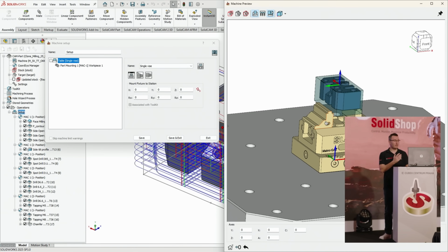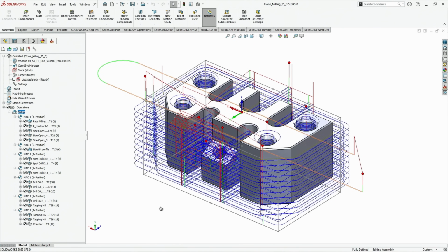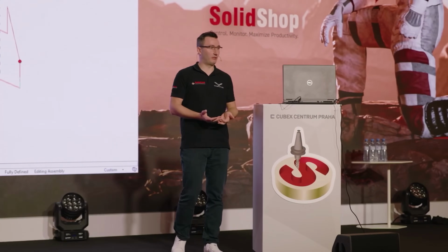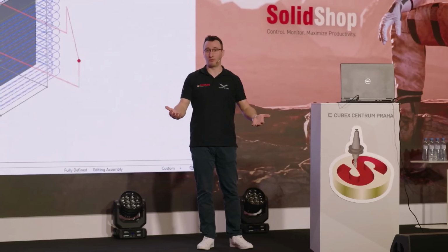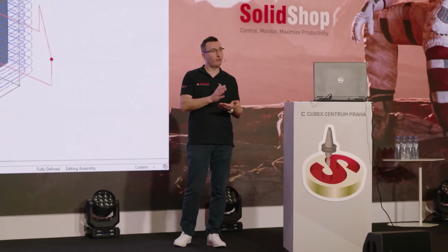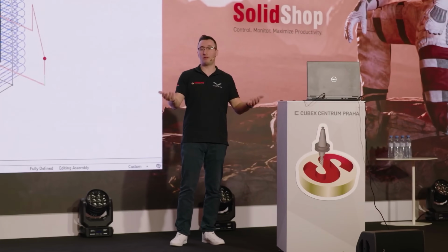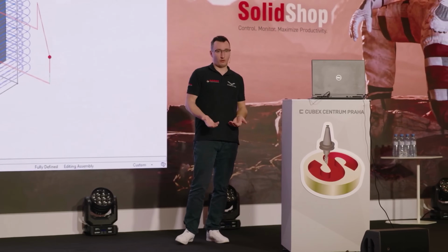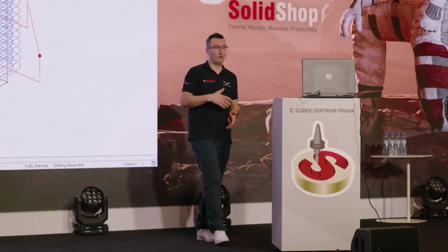So what is the delta that you need to do in the post? By default, the output will not come automatically, the application will not work automatically for your clones. Why? Because all our existing milling customers would maybe like to use the clones, but you need to do this delta to ensure that nobody will crash the machine. What is it all about? It's about the work offsets. We never had the work offsets, and it's a very big and important deal in clones. So you need to define them.